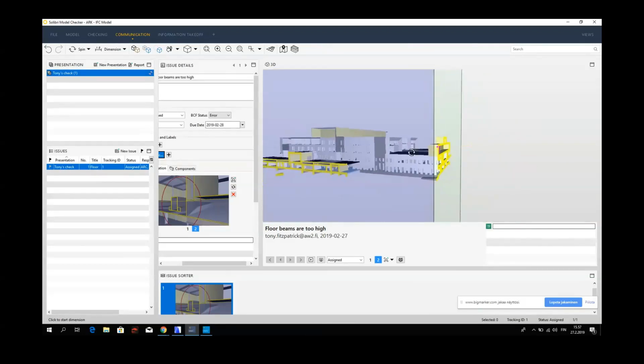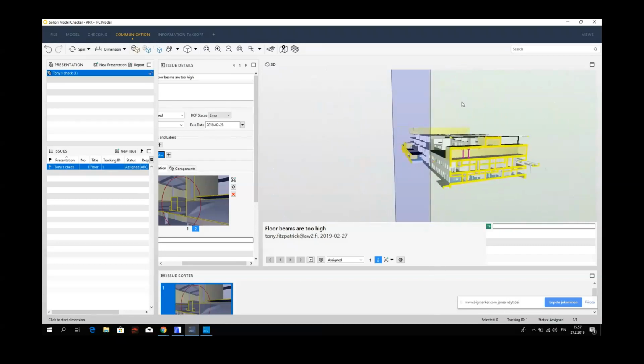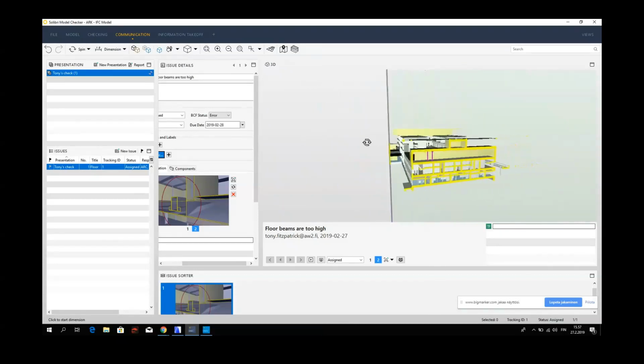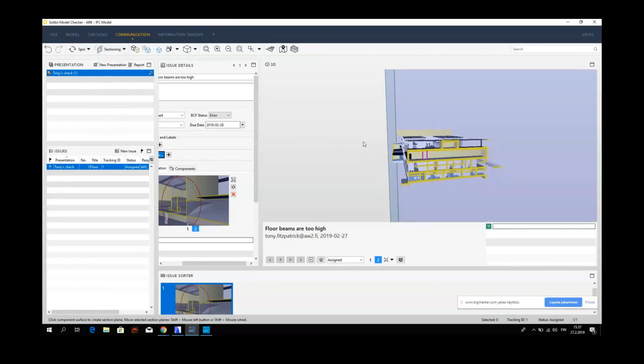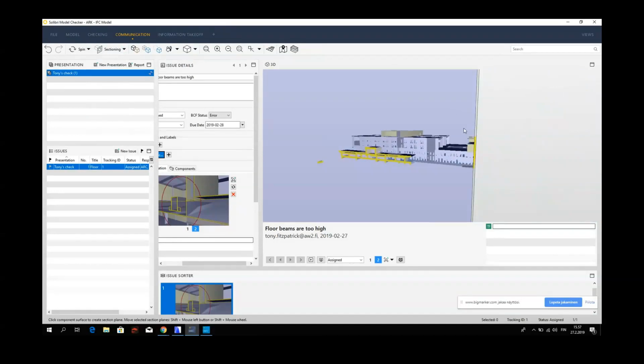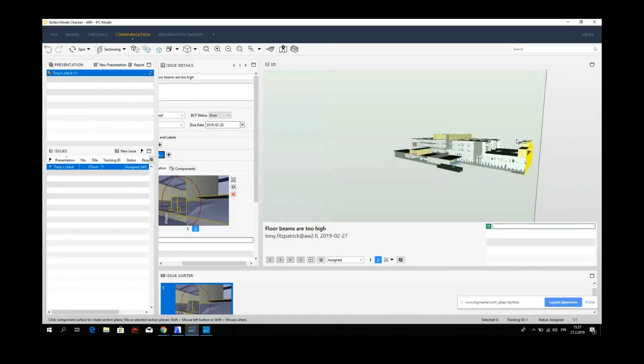Now, say you want to get rid of your section lines here, so I don't want that one anymore. You just need to click on, or get in the right angle. So you need to have sectioning turned on. So now when I click on there, I choose which section I want to get rid of, and then delete, and it gets rid of the section line.